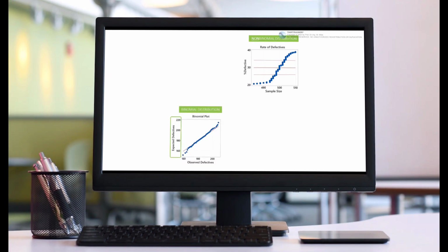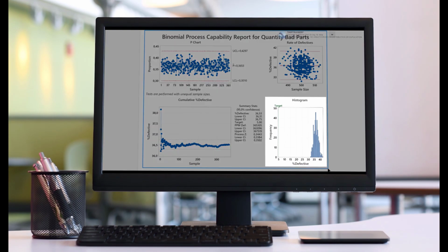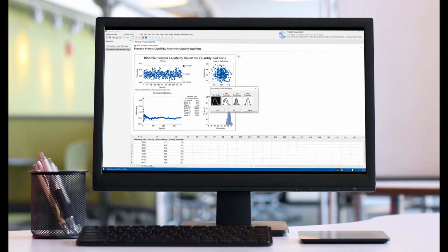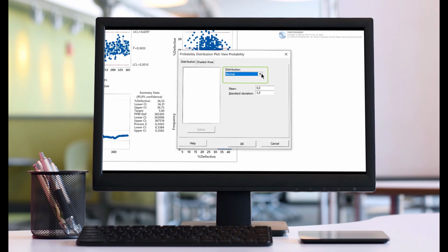With these findings, we can then carry out the necessary process stability analysis as a preliminary stage to the actual process capability analysis, in order to ensure that the necessary process stability is actually guaranteed. For this purpose, we will use the corresponding control charts, such as the P-chart and the NP chart, which take into account the laws of binomial distribution.